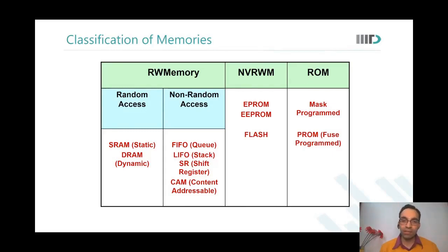some additional features into my chip, or enable a new set of features which are there in the debug mode today, but once we validate them on silicon, we will want to enable them. So the first few lots, the first few months, you give only the vanilla feature. You program the EPROM in such a way that only the vanilla features are available. And one year down the line, when you have well tested the additional features you had on the chip, you offer them also to the customer by just changing the program on your EPROM. So they're also used.